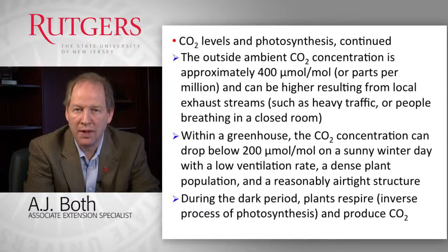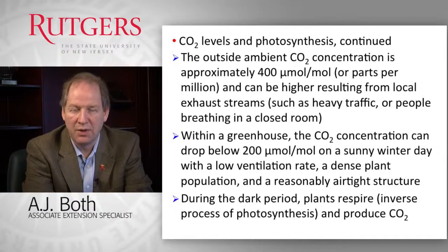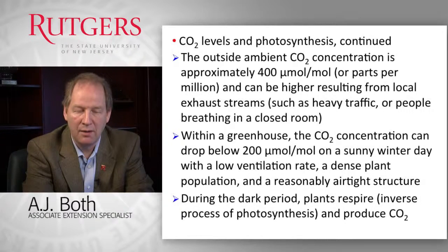In greenhouses that are closed and not very well vented, and we have a lot of plants that are using CO2 for photosynthesis, we sometimes see concentrations drop to very low levels. And when the concentration drops below 200 parts per million or micromoles per mole, we can see markedly reduced plant growth rates just because of that. This is something that can occur on sunny days in the wintertime when we don't need to vent to maintain temperature. And the plants are obviously using a lot of light for photosynthesis and also require a lot of CO2 in that process. So under those conditions, we typically see low CO2 concentrations, and it typically helps a lot if we increase the CO2 concentration, because it improves photosynthesis.